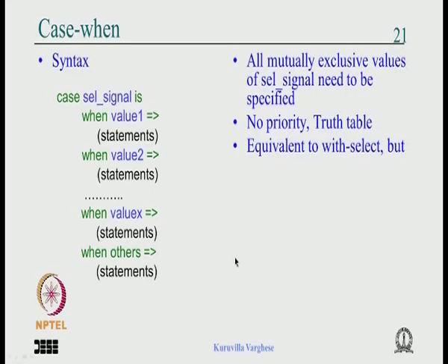So let us turn to the slide. This is the syntax of the case when. This is equivalent to the with select of the concurrent statement. The syntax is: case an input signal is, and when value 1, a numerical value of this select signal, you do the assignment statements. Various appropriate statements can come here, and when value 2, and at the end you say when others, which means whatever is not included is combined together in others.